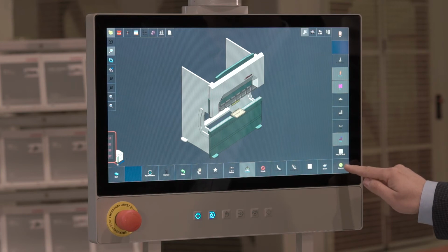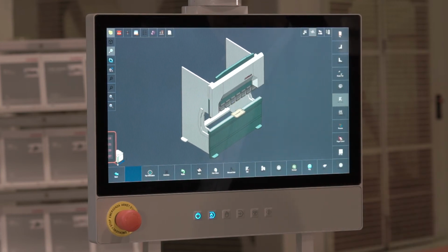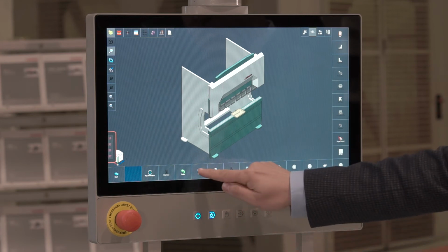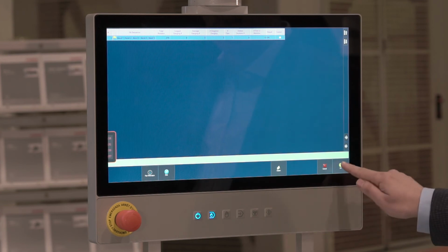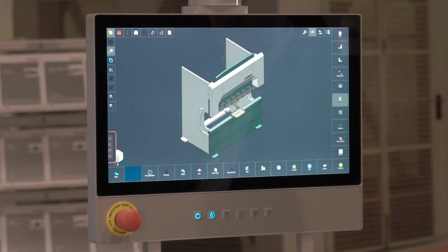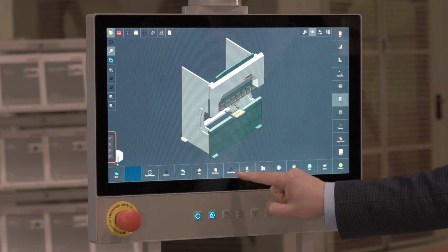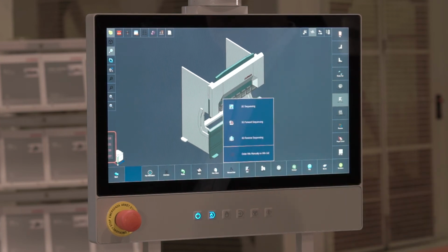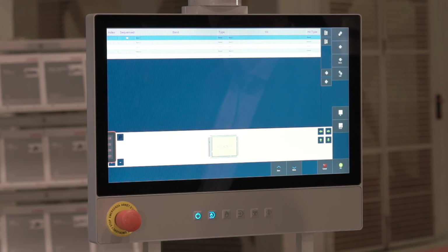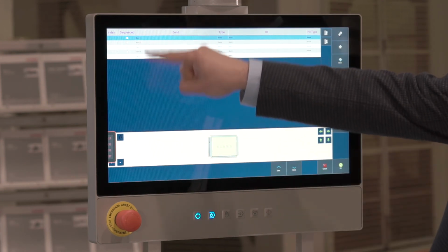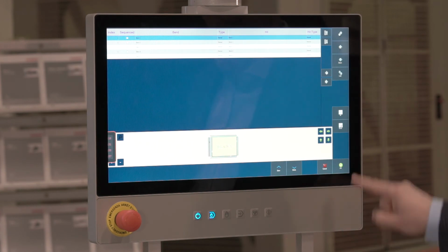We activate the sequence button for bending sequence processes. Then, we activate the simulation screen by pressing the Auto button. Now, the control unit of the machine shows us that we can use these tools for the bendings we want without any errors. We confirm. We display the bending sequence we made during the design with the manual order button on the machine. This 5-step bending is now on our screen. We confirm.